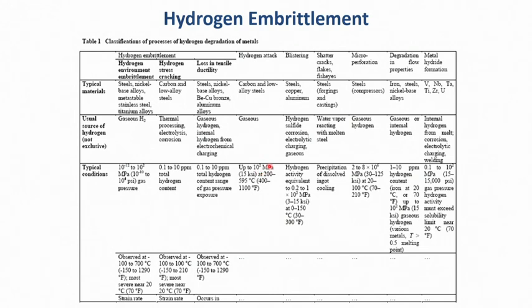where pressure is even higher. Blistering is a phenomenon observed in steel, copper, aluminum based alloy, where the diffusion of hydrogen atoms through the component is responsible. There is diffusion of hydrogen atoms, and they convert from diffused atoms to molecules and then apply pressure. By that process there is a lot of swelling in the component when it exceeds the yield strength of the material, and you will find local blister formation inside the component.